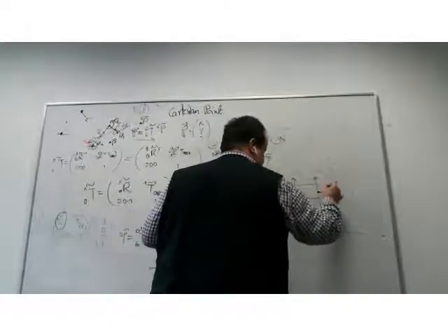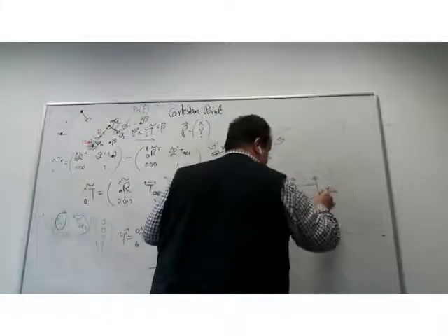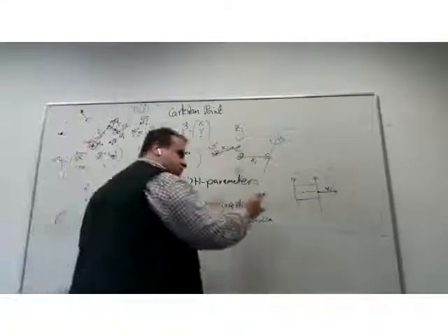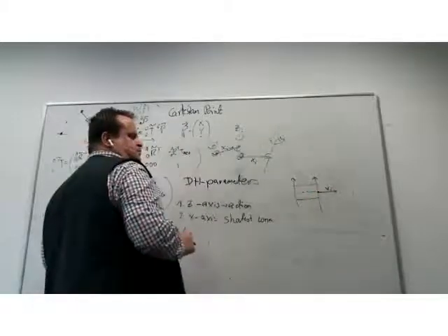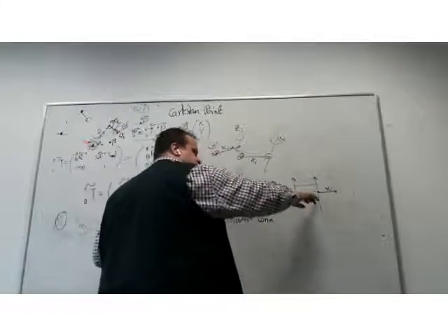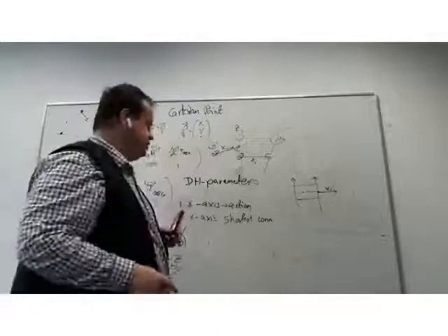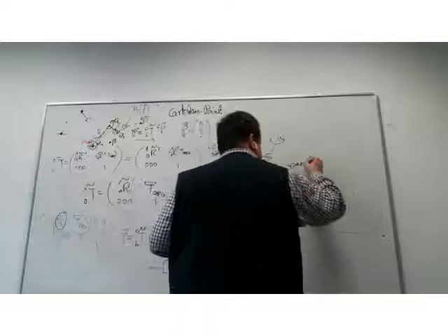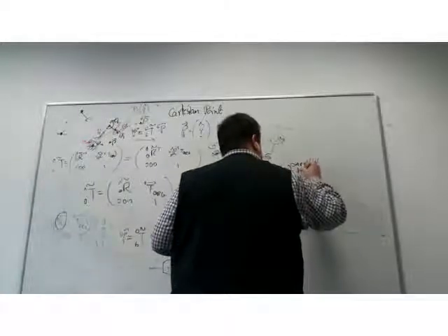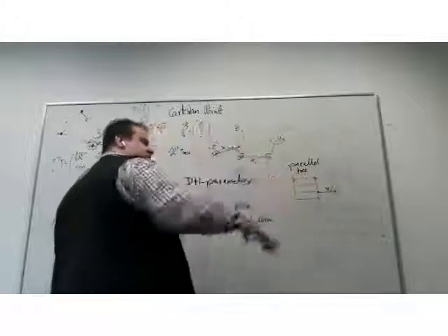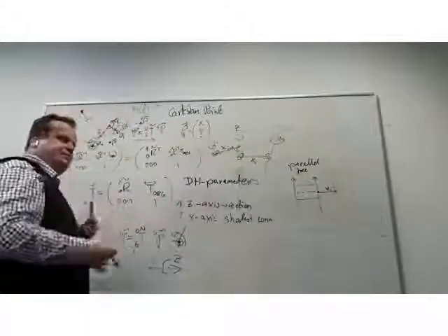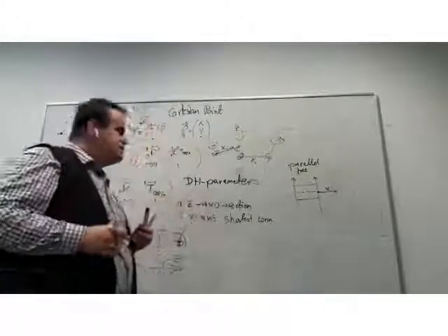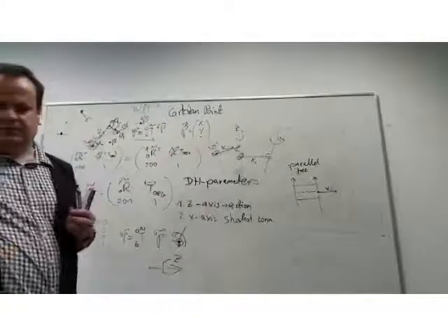But if my xi is at this point, usually I try to place it in such a way that I don't have offsets here to continue. So for the parallel case, I'm doing the choice, but I'm trying to align it with the previous or with the consecutive x-axis in the system.